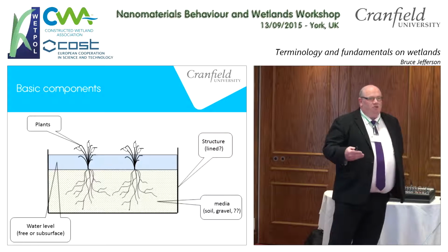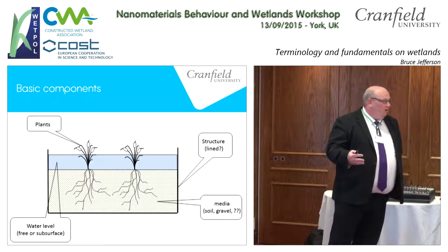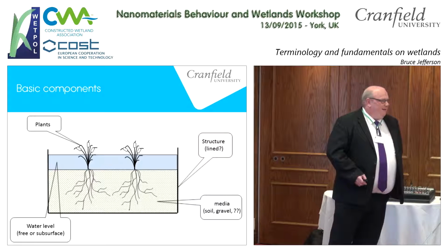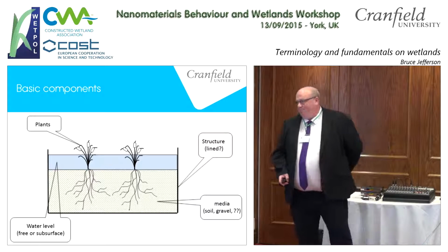If I'm doing it as a treatment technology and I'm constructing the wetland, then I will tend to line it so that I can control the flow, I can control where the water goes. In the natural systems I would tend to not. There obviously would be no lining unless there's a natural clay lining in the soil structure.